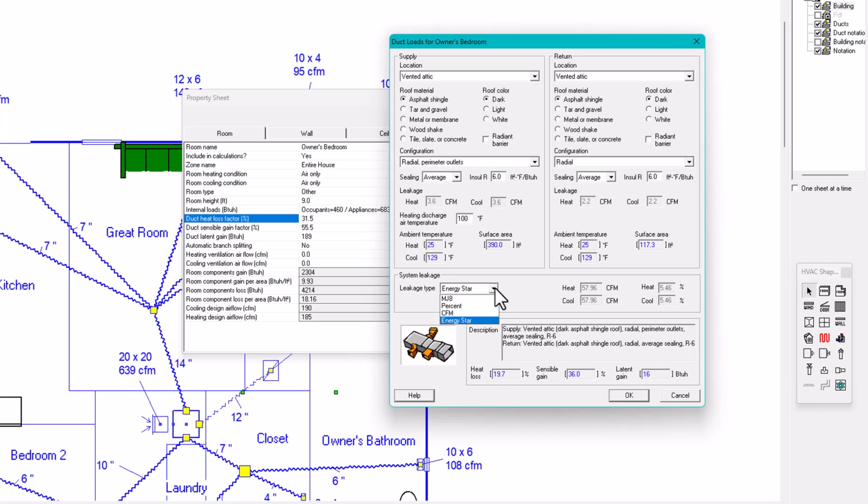But again, just to be safe, the homeowner is not going to complain if the system is cooling too much and it's very cold. They always complain if it's not cooling. But you don't want to oversize at the same time. If you need a 2.5 ton unit for a house, you don't want to say, let's be safe, let's put a 5 ton unit, because you would have short cycling and more issues. So that's why we're going to put in the default and be conservative like this.